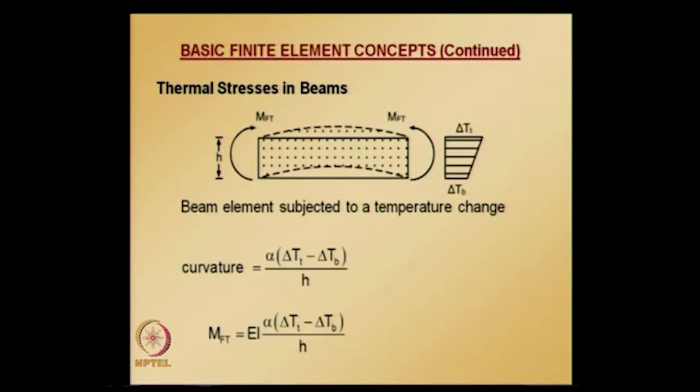The equivalent load vector for solving the transverse displacements and rotations requires a sign change to the vector that we get from fixed end solutions.